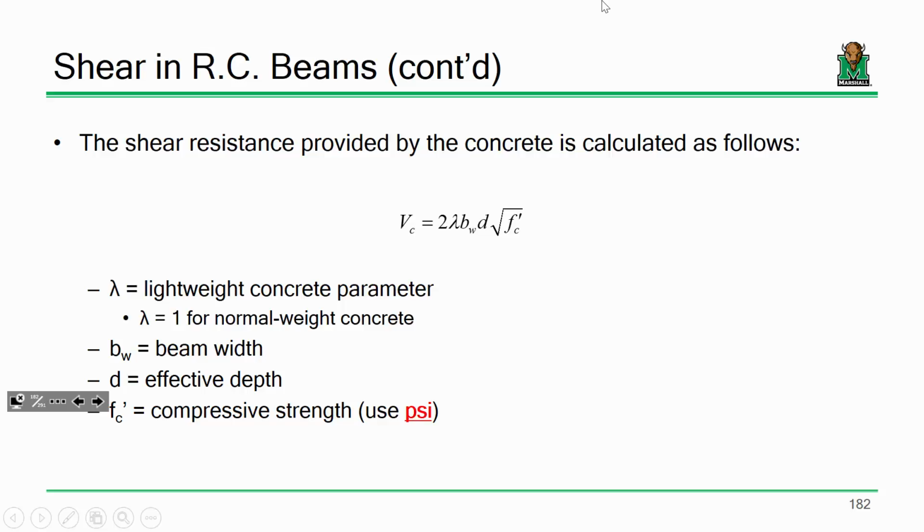All right. So last time, if you recall, we were discussing shear. We ended our discussion of doubly reinforced sections, and we got into the world of shear. I showed you some videos, and we talked a little bit about the behavior of concrete in shear and how it cracks at 45-degree angles, and when it fails and cracks, it goes quick, so its phi value tends to be a little lower.